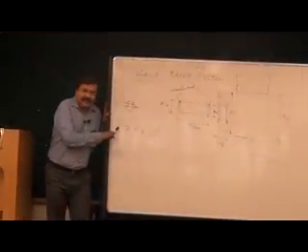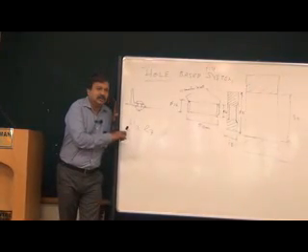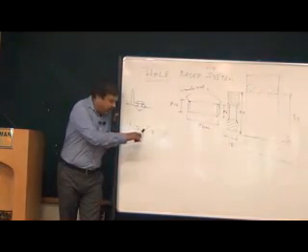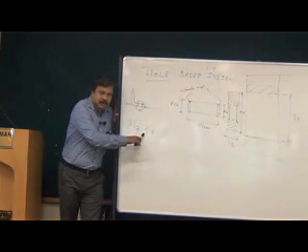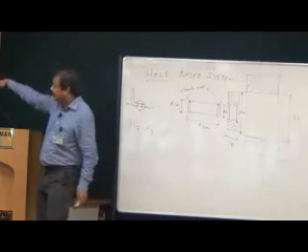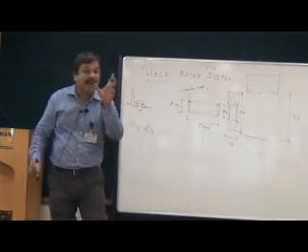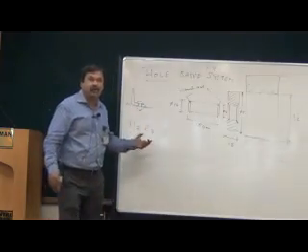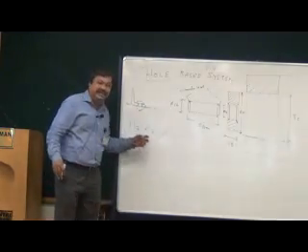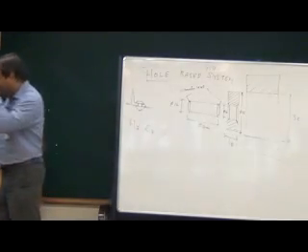So this capital letter stands for the hole feature. The small letter stands for the shaft feature. So based on the type of fit you want, you choose a particular tolerance pair. H7 E7 is called the tolerance pair.